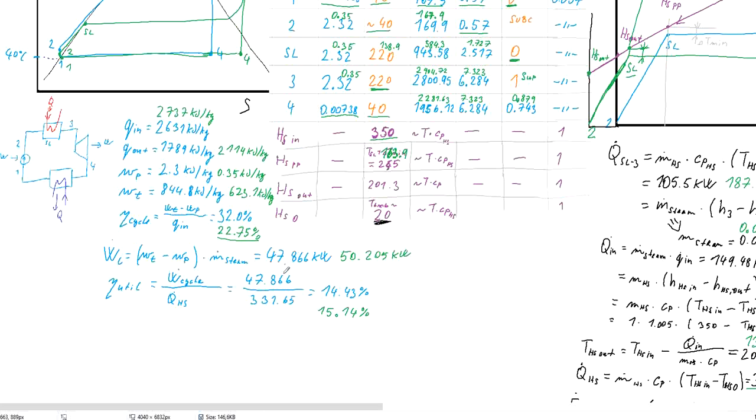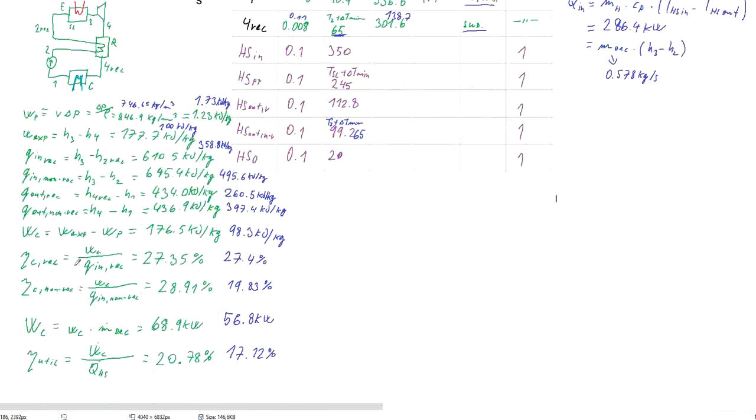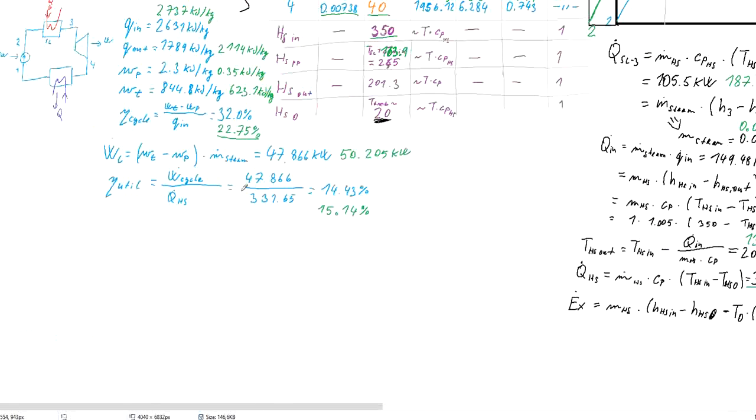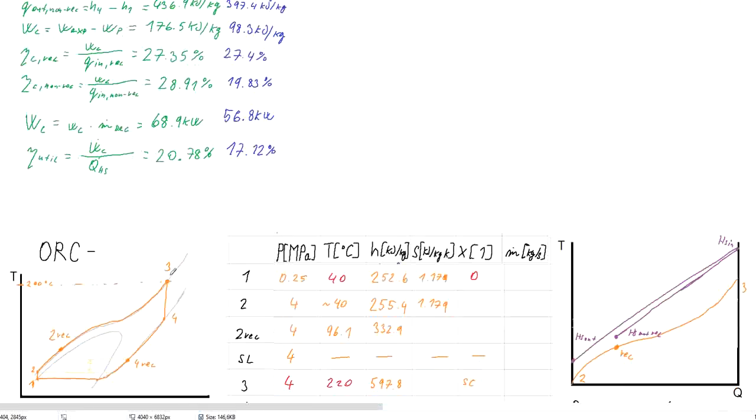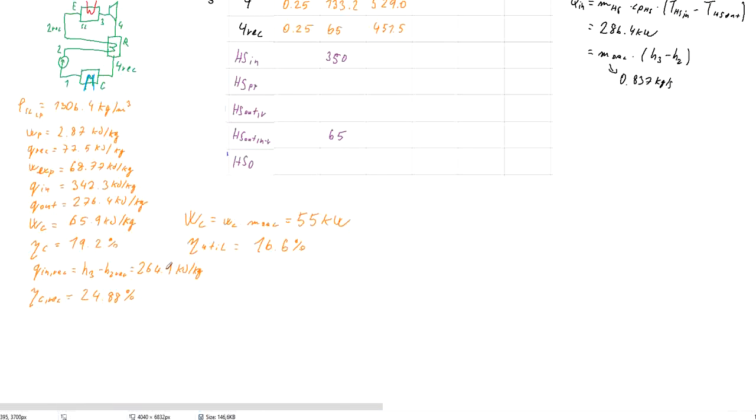When we have a look at just the efficiency of the cycle, here the values are different. Steam cycle 32% with expansion from the saturated liquid. The low pressure steam cycle 22. For the Toluene, the efficiency is around 28%, so still less than was the steam cycle with the 32, but much better performance, much better power output in the waste heat recovery.